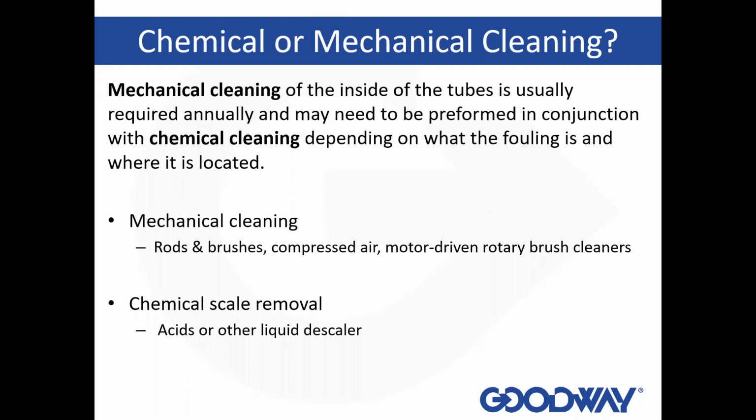Most of the time you're going to use a user-friendly type. We make a product called ScaleBreak. And the idea is that it's not going to attack the metals around it, but it is going to attack that calcium and start to dissolve it and put it into the water stream. And the way that you do this is not just by pouring it in and letting it sit there, it actually has to circulate in order for it to work properly. And we'll talk just a little bit more about that in a minute.